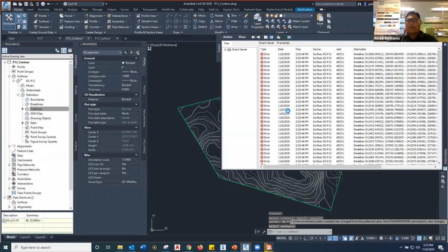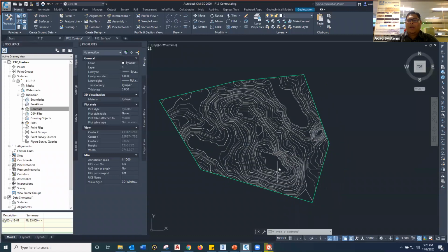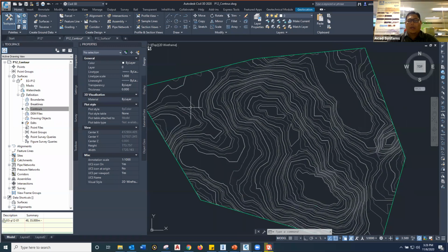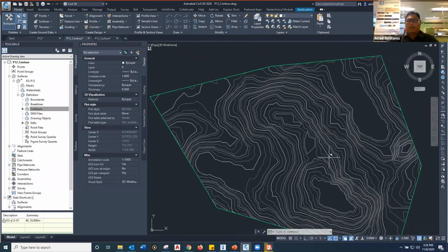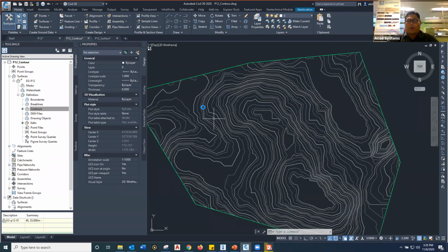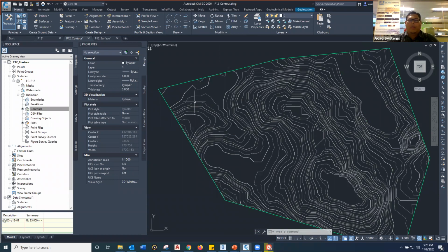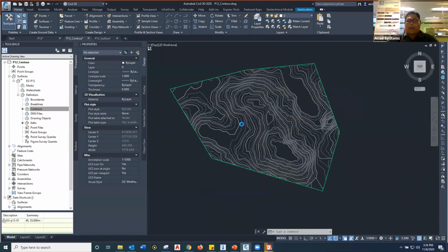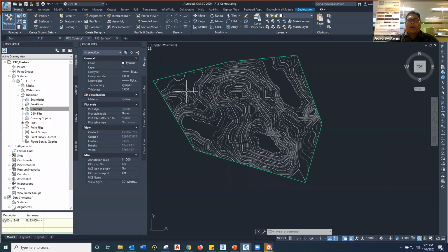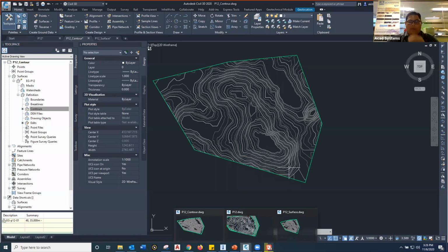And you'll definitely get these error messages because you have deleted the minor contour lines, and this is what we'll get. But you don't have to worry too much because you can also clean it back. Make sure you don't delete the necessary contour lines, simply delete the data that is unnecessary, like all the spiky lines, so that it will help you to get a smooth contour line. So once you create, you get the surface generated from this.